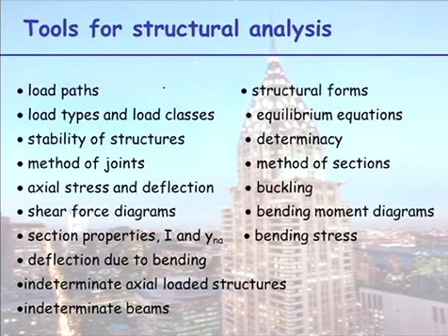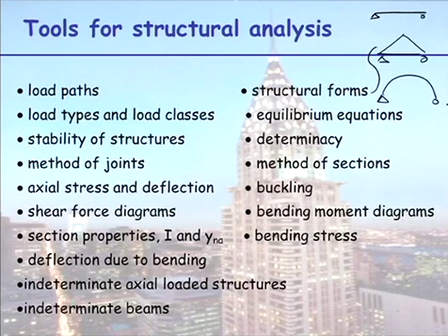So you know we have to follow load paths from their starting point down to the ground to see where the loads transfer to. And we know we have different structural forms. Loads can be transferred through beams, through truss structures, through arch structures or through some sort of cable structure. So the loads, whatever they are, will transfer through that structure. How they transfer through that structure, whether it's bending, shear, axial compression, axial tension, is a function of the structural form.